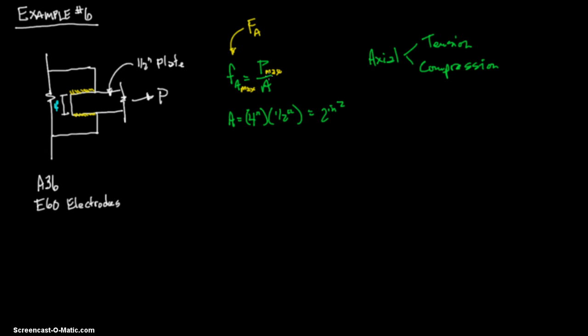All right, so let's go in. Now we have A, which we'll fill in, but we also need our capital FA, the axial stress. What is your axial stress? And let me look at the tensile stress in my steel book. What's the allowable? To tell you the truth, I just know in allowable stress design that it's 0.6 Fy, which I'm going to go ahead and write out. I'm saying that FA, your axial stress, equals 0.6 Fy.